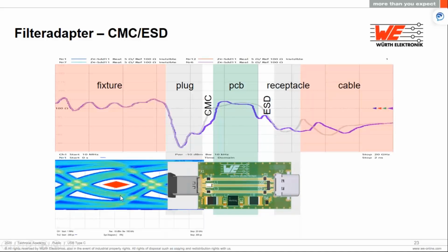at all. And lastly, what we see is that these microstrips, so far we saw that they were not coated with anything, or there was no layer of protection applied over that. The reason is that the protection coating will also have some kind of epsilon R, which can manipulate the functionality of the signal.